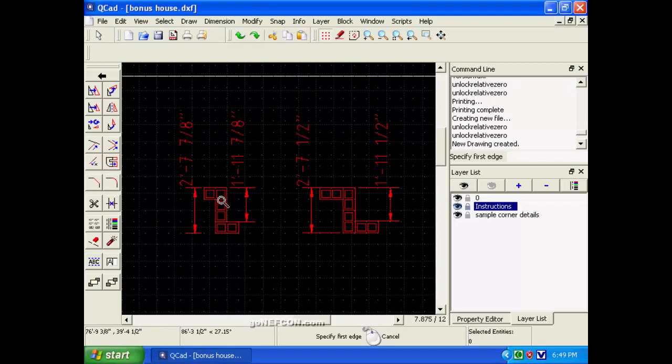What we have here is 1, 2, 3 concrete blocks that forms an outcrop. And here we have 1, 2, 3, 4 concrete blocks that forms an outcrop. You notice if this was row 1 of the block wall, then this would have to be row 2, and vice versa, because you can never have the joints where the blocks join together appear at the same place on 2 successive rows. Notice there's a full block across this crack, and down here there's a full block across this crack, and then this crack has a full block across it on the next row.